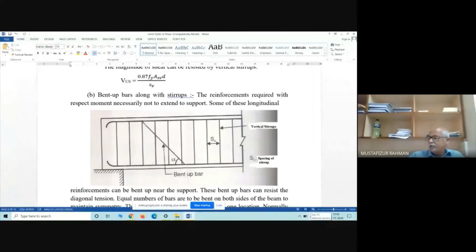There is a possibility of compression. The upper rod will be subject to compression. See, the diameter of the rod is very small. So the compressive stress is acting along the longitudinal axis of the compressive rod. So it is a compression member. The permissible compressive stress or maximum compressive stress of a compression member is dependent on the slenderness ratio.